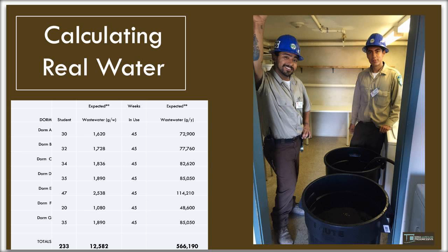And one of them was from a laundry machine that was rated as a low water use machine, rated around 11 to 17 gallons per load, and yet we couldn't get our system to disperse all the way to the end, and it ends up that it was using between 3 and 5 gallons per load when we actually tested it.